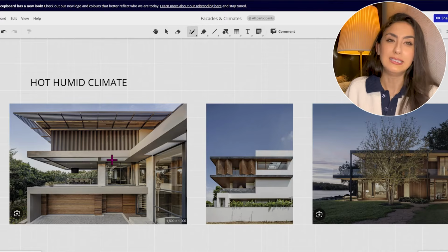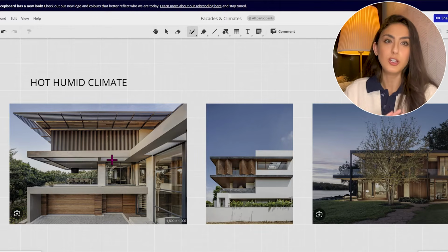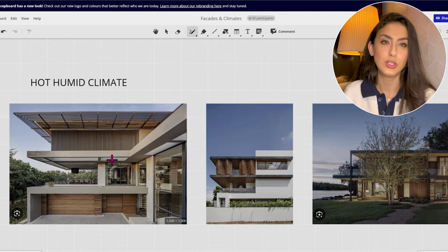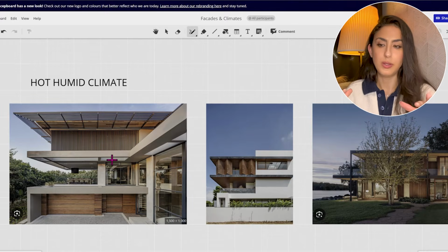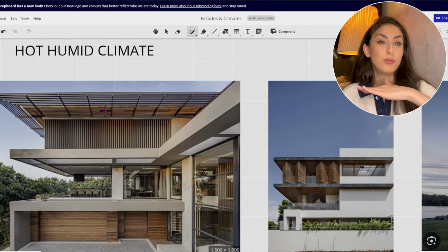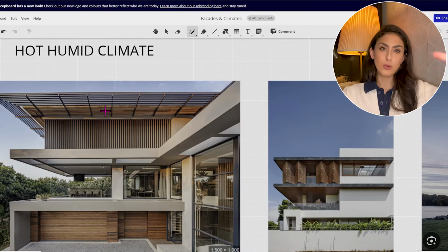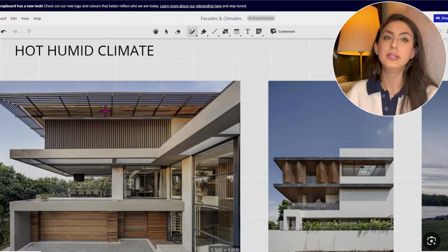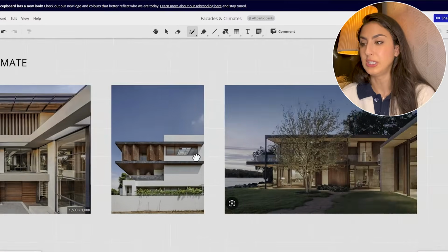It also rains. That's the tricky part, because it rains there a lot, so you still want to let all that air come in even while it's raining. So if you can have those windows that are called jalousie windows, where they're horizontal lines where you can let all the breeze in even while it's raining, so you don't ever have to close your windows completely. They use a lot of overhangs, because you want to extend the overhang so you're not getting all the sun glaring at your openings, so at least you want to provide some of that shade.